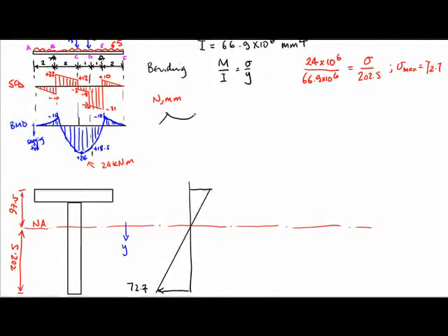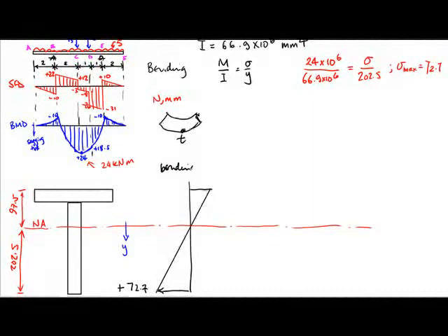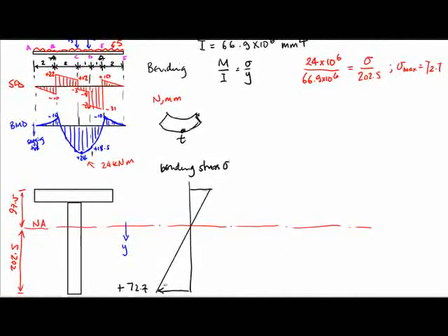So if your beam is sagging, then at the bottom of it, that will be in tension because you're stretching the material there. So this will be a tensile stress. So this will be a distribution of the bending stress sigma, and all below the neutral axis, it is in tension at location C in the beam.